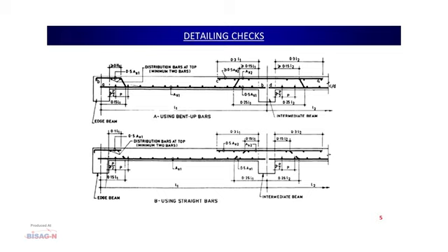Here you can see the main steel, or ST1, that is the main steel of the slab, should be provided at the bottom. We have to ensure that the bar binder does it like this. The main reinforcement should be provided at the bottom and the distribution steel should be taken above this. Many times the bar binder makes the mistake of providing the distribution reinforcement at the bottom and the main reinforcement on the top. That is not recommended to be done at the site.